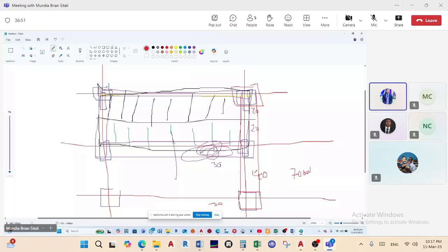For instance, if we look at this, we say our spans are 5 meters. So you may have to reduce maybe to 2.5, so that you essentially reduce this to a 400 by 400 column, and it may work because then the load has been reduced. Yeah, so all the columns are abstract. So we come to, I hope I've answered your question now. Yes, you have.